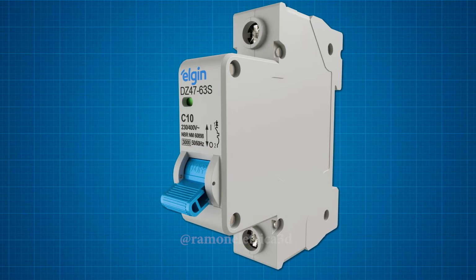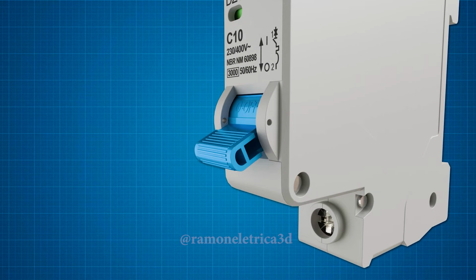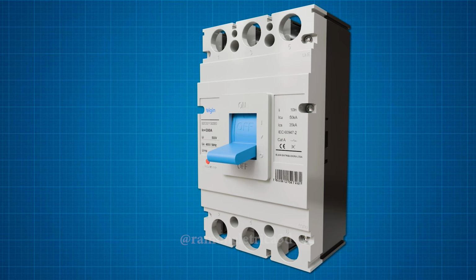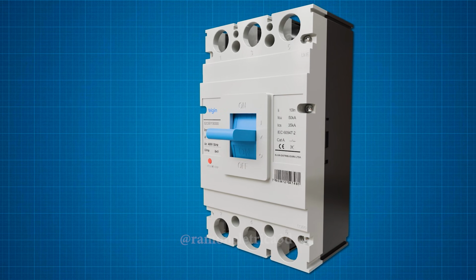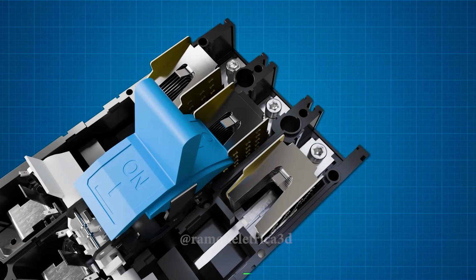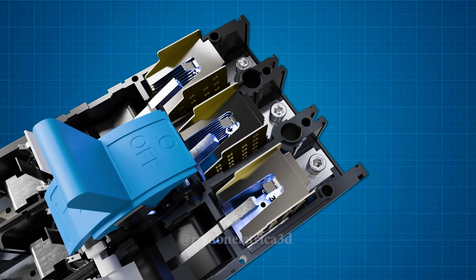Another difference is in the switching mechanism. MCBs have only two handle positions, up, on, and down, off. MCCBs, on the other hand, have three positions: up, on, down, off, and a center position. This center position indicates that the breaker has tripped due to a short circuit or overload. So with this type of breaker, when a fault occurs, you can identify it by the position of the handle.